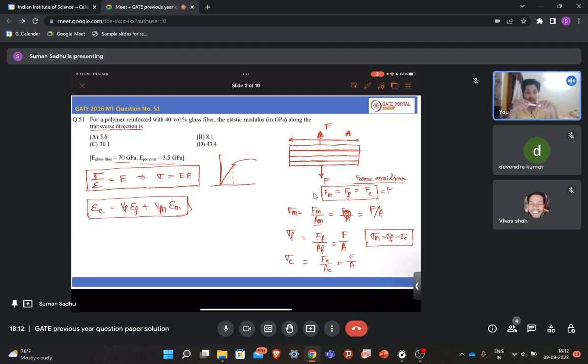You know what is composite, right? Composite means, let's say there is a polymer and you have put glass fiber inside. Or you can also take a simple example like the wall inside of a home in the village area, where they use bamboo and mud to prepare the wall. That is the same kind of structure as a composite. There, one is a matrix phase, which is relatively soft, and another one is the glass fiber or fiber phase, which is relatively hard.